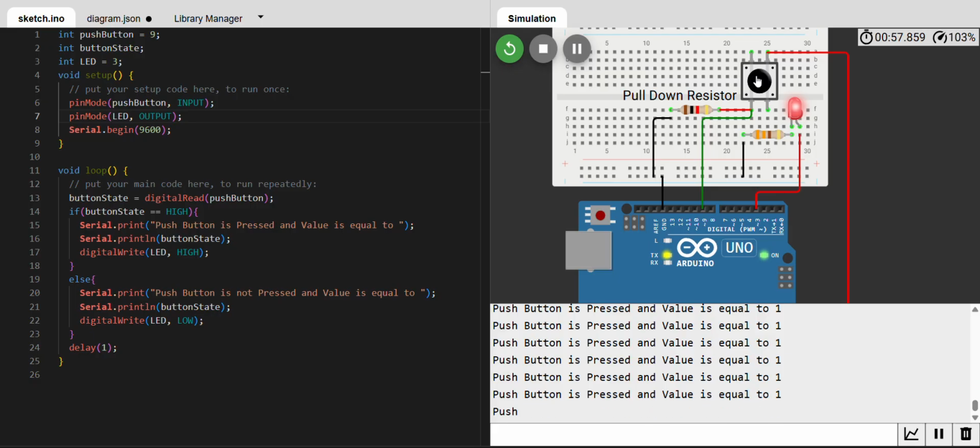Instead of going completely to the LED, it will absorb some of the voltage as a voltage drop across it, and will send only 1.8 to 2 volts of supply to the LED, which will make it glow without any damage. Like this the LED glows on.